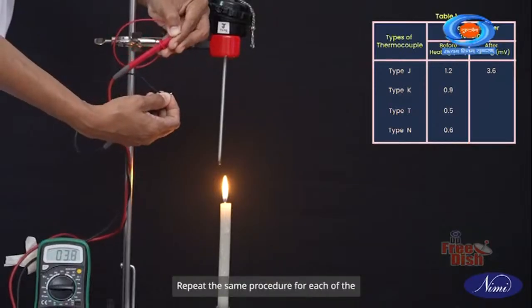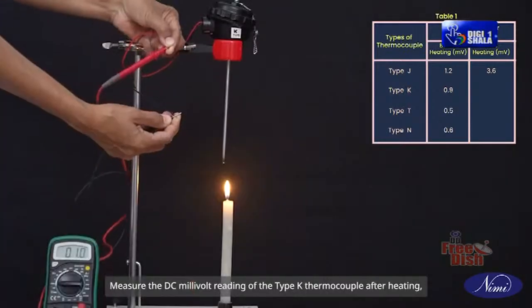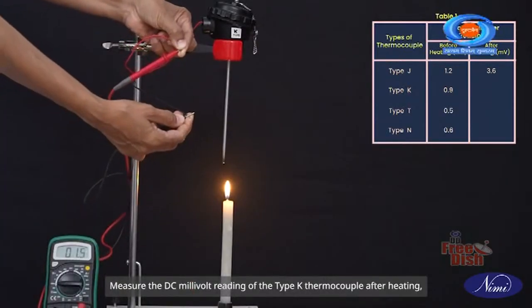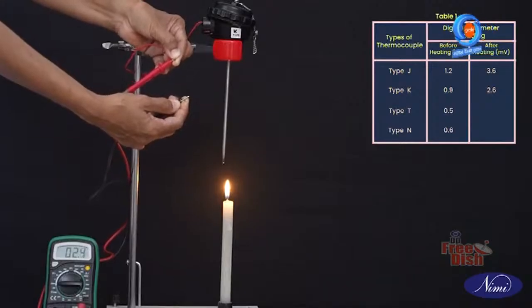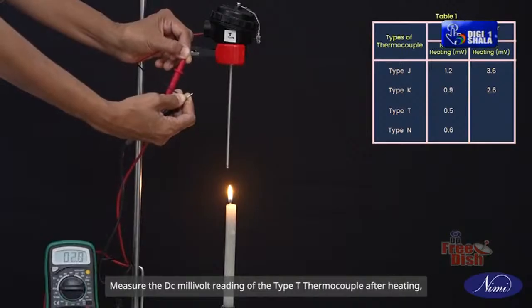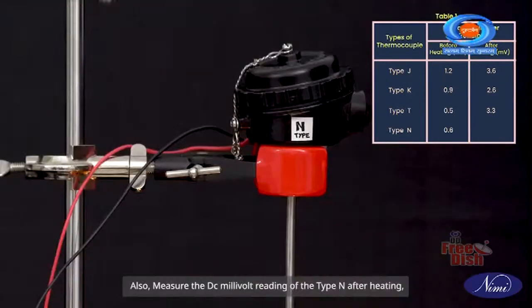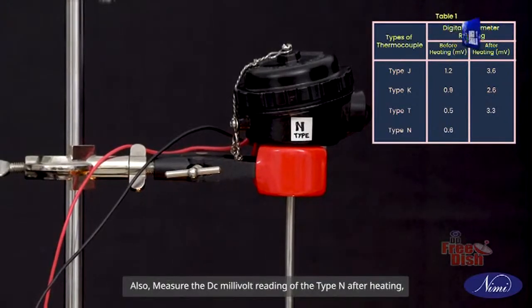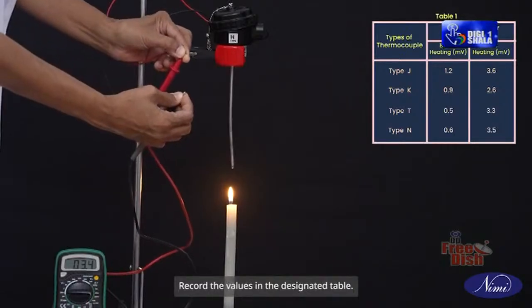Repeat the same procedure for each of the different sensors. Measure the DC millivolt reading of the type K thermocouple after heating. Record the values in the designated table. Measure the DC millivolt reading of the type T thermocouple after heating. Record the values in the designated table. Also measure the DC millivolt reading of the type N thermocouple after heating. Record the values in the designated table.